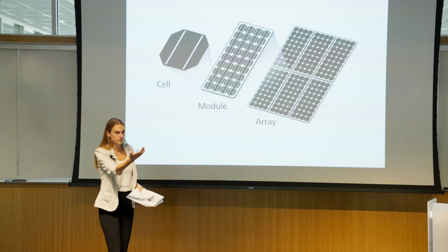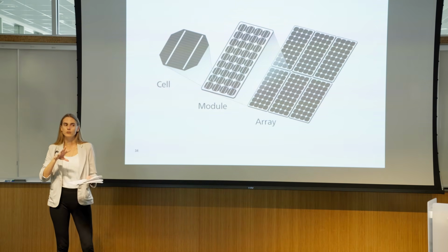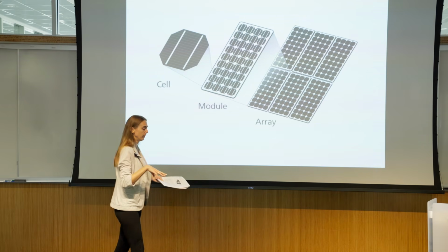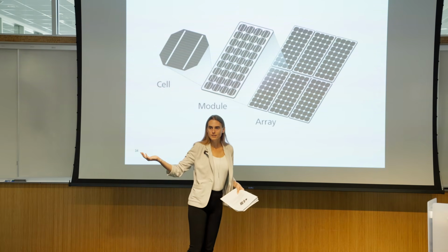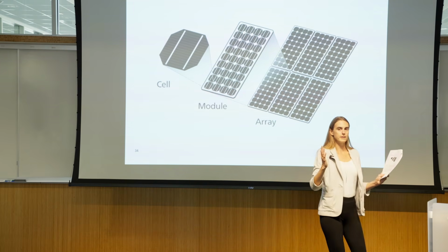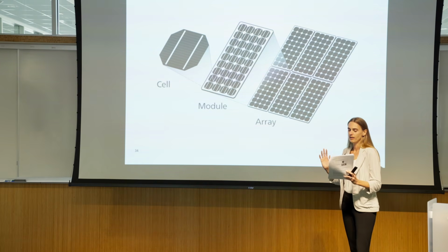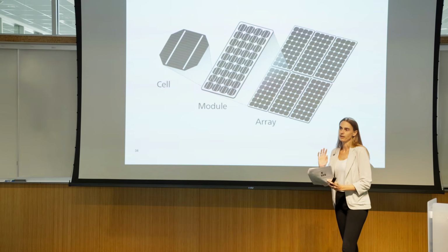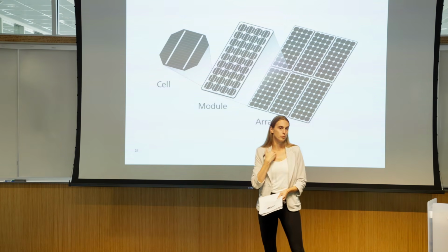And this is one of the reasons why, as we talked about earlier, consideration of shading at your site when you're building a project is really important. If you have mountains next to your project, or you've got trees, or even if you're placing your arrays too close to each other, they could shade each other, right? And significantly reduce the power output of your project.